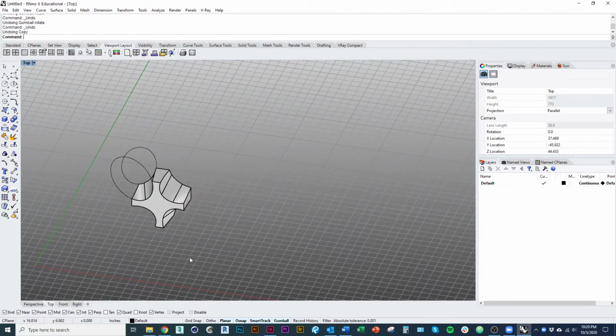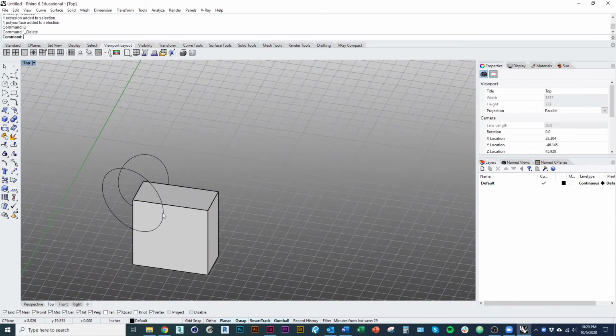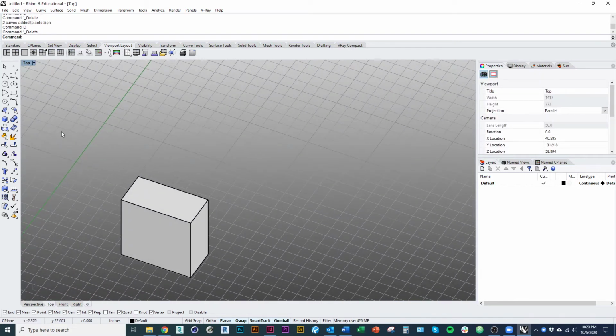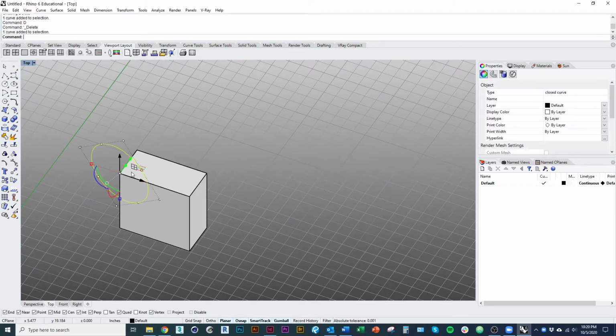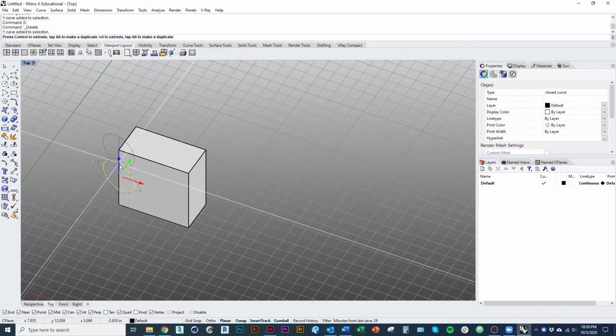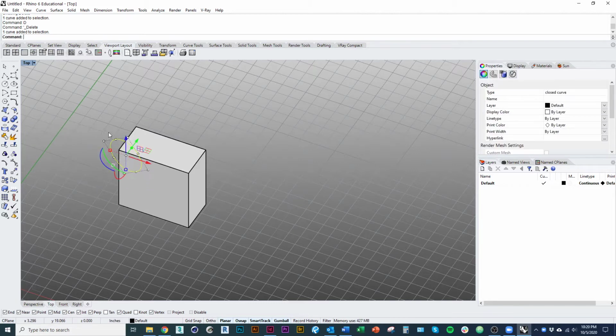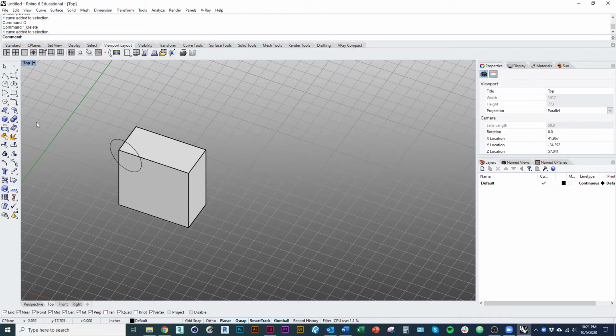And then one other technique I want to show you guys, a little bit different than the loft, is to do something called a sweep. I'm going to draw a, so I'm going to make this a little small, and I'm going to kind of move it through my volume. Now this is going to be one of the more advanced techniques. Keep in mind you want to actually make this into a physical model, so just be mindful of using kind of weird dimensions and making it in a way where it's hard to figure out how to physically model it.